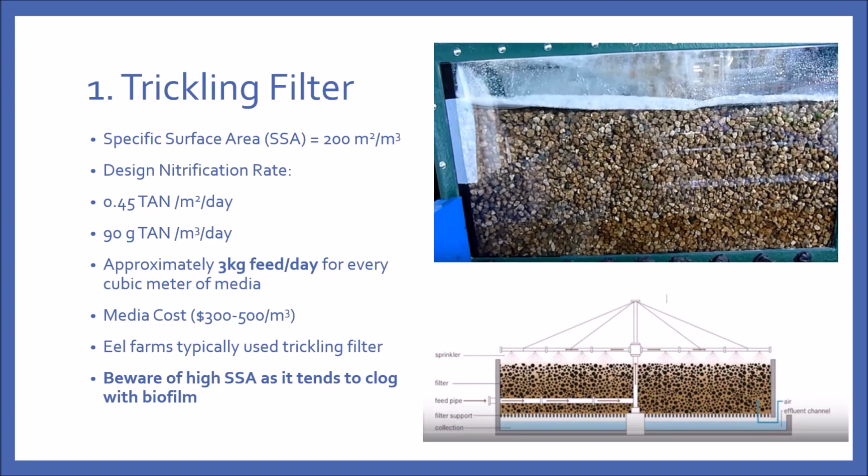So usually what do people do in this case? People tend to oversize 3 to 5 times bigger in terms of capacity and allow for the clogging to occur. So in this case, which is a wastewater trickling plant, you might need only 20% of your capacity, but you oversize them 3 to 5 times to account for this clogging factor.